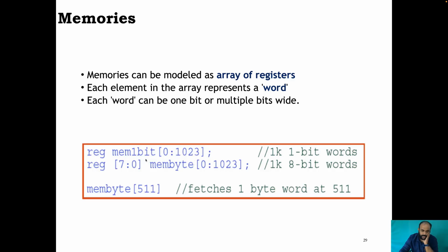In the first declaration, it is written reg mem1 [0:1023]. So it means you find the bit width specified after the variable name. So here it means the memory is nothing but an array having how many rows? It's an array having 1024 rows, and the first row, the number close to the left side bracket, is row position 0. And the last row is row number 1023. So altogether 1024 rows are there.